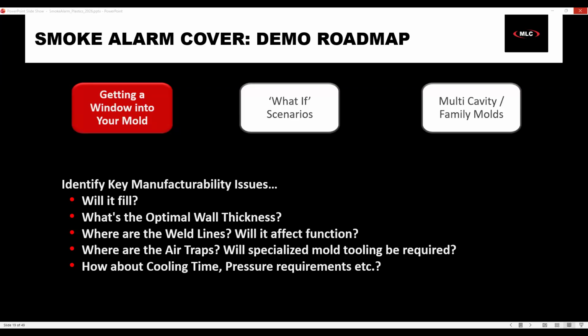But when you're working in FEA, that mesh is so incredibly important, and we have very specific criteria for that. Part of that reason is because it's doing a different type of analysis per node. This has a different kind of algorithmic function in the back end, so the mesh does not have to be quite as tight as you would have in an FEA analysis. What that means for you is less runtime and less time meshing.